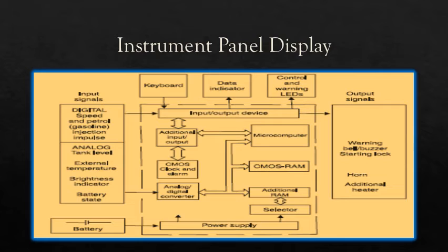Electronically erasable programmable ROMs are used to store information like the odometer data and other parameters for compensation of the temperature, fuel tank dimension, etc. This data is normally encrypted for security purposes. An example of a dashboard computer of a motor vehicle is shown in the figure.